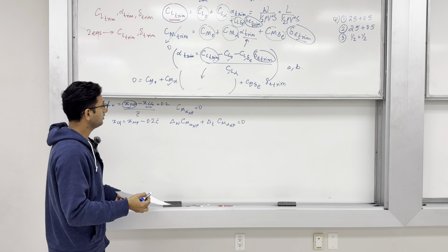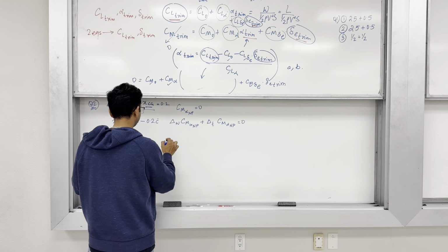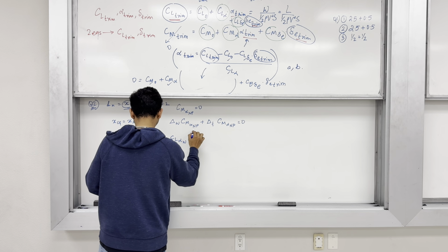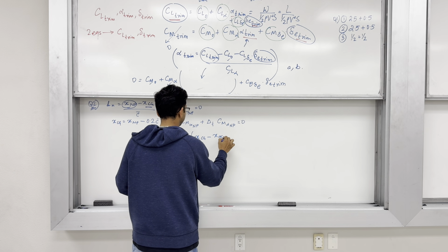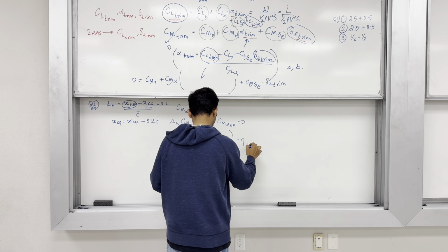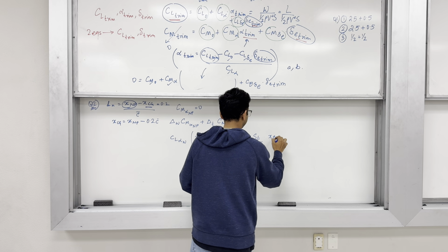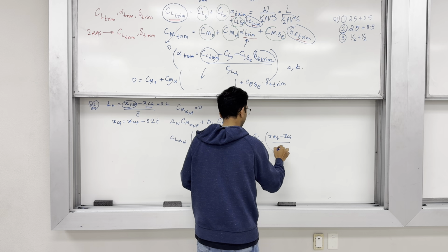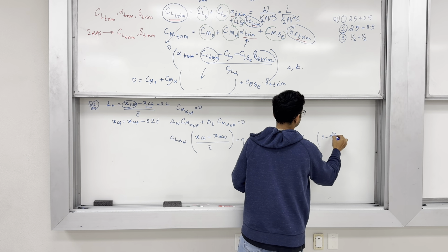Now, even if you did not note down the contributions for neutral point, it is fine, because you can simply write down the contributions about the CG. So, write down the contribution about the CG: x CG minus x AC wing divided by C bar, minus eta t S tail by S times x AC tail minus x CG divided by C bar times CL alpha tail times 1 minus d epsilon by d alpha.